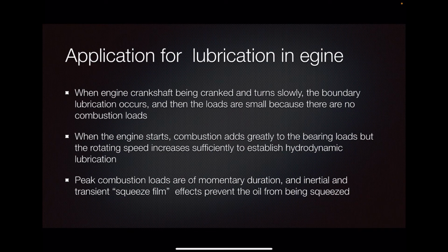The last topic is an example for lubrication in engine. When the engine crankshaft is being cranked and turns slowly, boundary lubrication occurs, and the loads are small because there's no combustion loads. When the engine starts, combustion adds greatly to the bearing loads, but the rotating speed increases sufficiently to establish hydrodynamic lubrication. Peak combustion loads are of momentary duration. The inertia and transient squeeze film effects prevent the oil from being squeezed out.